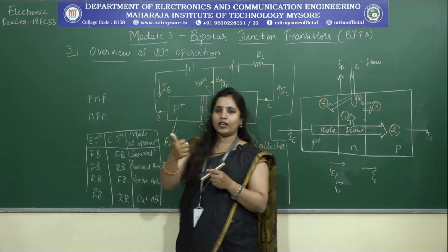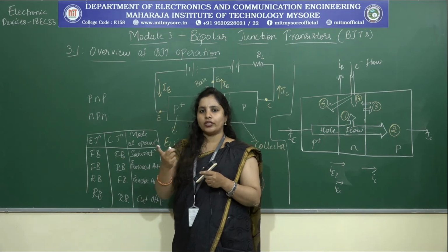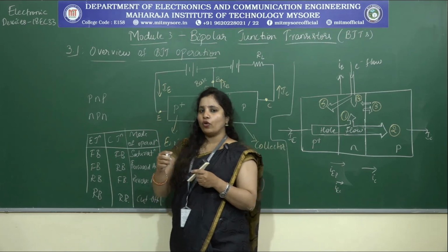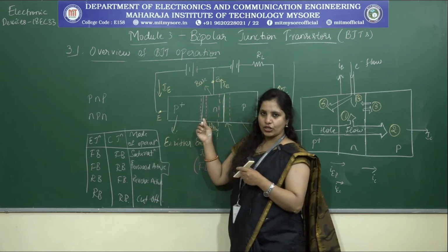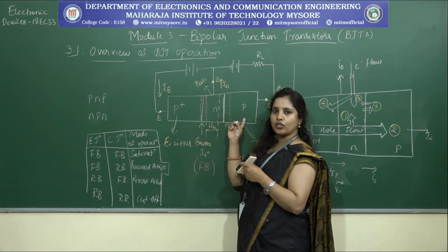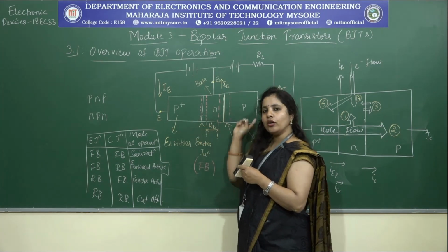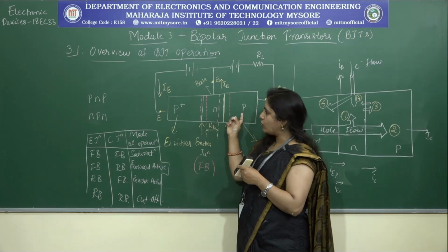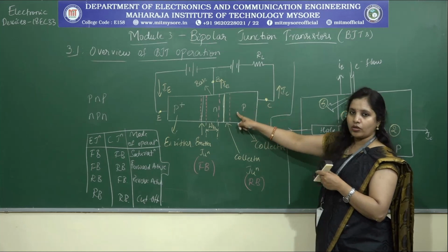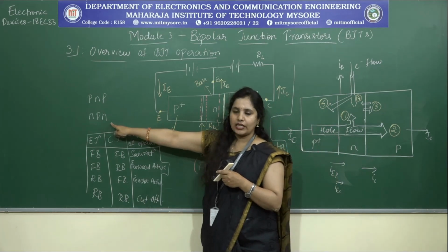We started off with the optical generation and then we tried to find an alternative solution. What was the alternative solution? It is to have a source of hole injection, and that source turned out to be the P plus N region. Making the N region common between this forward bias junction and reverse bias junction, we formed a BJT. We understood the constructional details, and also looked into the different current components that can flow in the given BJT. What BJT did we consider? It is the PNP.